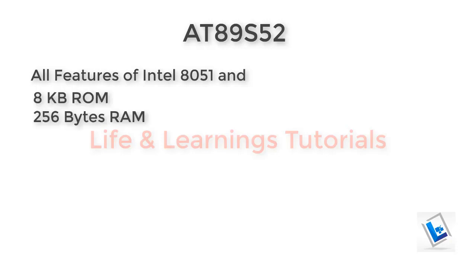On the other hand, if I consider Atmel's AT89S52 microcontroller, then its memory is extended and we will get 8 kilobytes of in-system programmable flash memory or ROM with 256 bytes of internal RAM instead of 128 bytes. So we are getting double the ROM and RAM in Atmel's AT89S52. And there is one extra timer, timer 2, in Atmel's 8051.